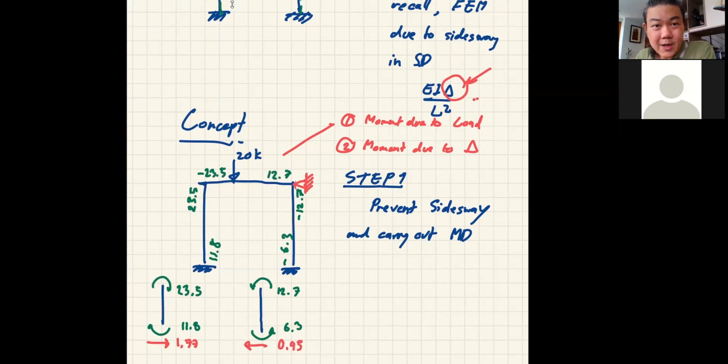Okay, just look at this. You see, if we don't have this lateral restraint here, if we don't have anything here, you just look at the reactions you have. Remember that this frame does not have any force in X direction at all. So in the normal world, the summation of these two reactions should give you 0, right? But then it doesn't. So that means the difference between these two reactions becomes the reaction here. That is 0.82.